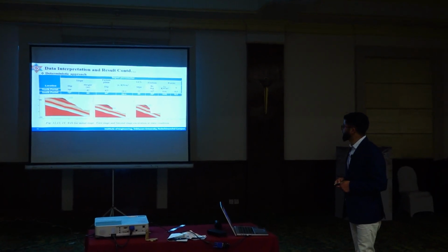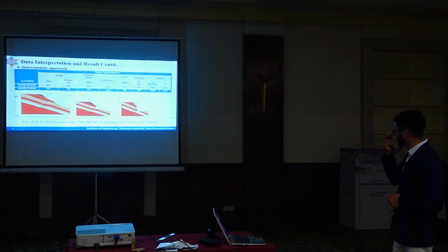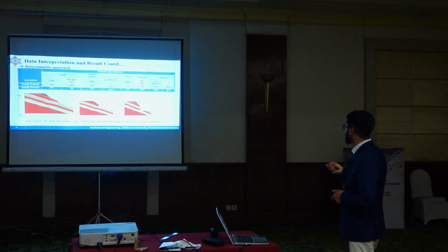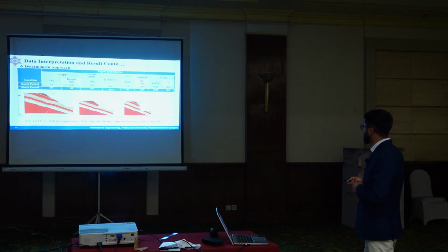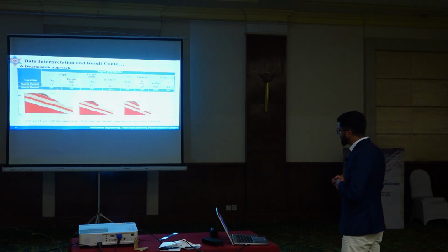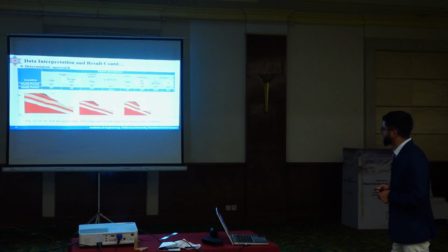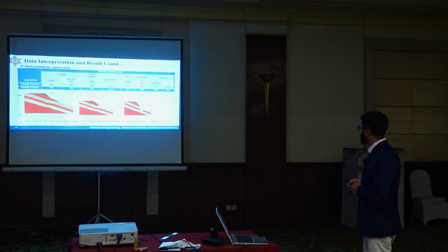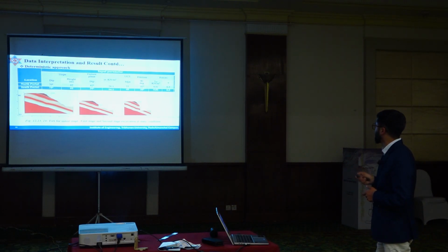Deterministic approach. Slope stability assessment was carried out with the deterministic approach using Slide2 software. These are the input parameters for the Slide2 software. And this is the result from Slide2 software. Here the initial condition, that is before excavation, the factor of safety is greater than 1, which we can see in the figure. Here at the first stage of excavation, the factor of safety decreases below 1. And here at the second stage of excavation, the factor of safety further increases due to the benching effect.